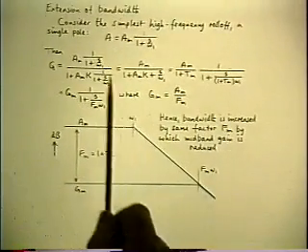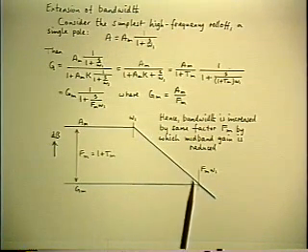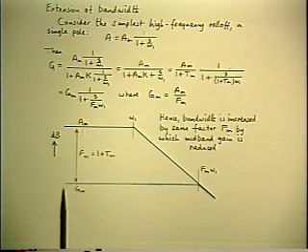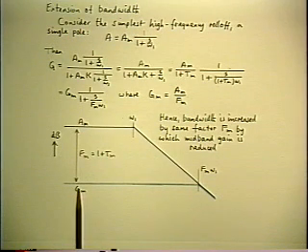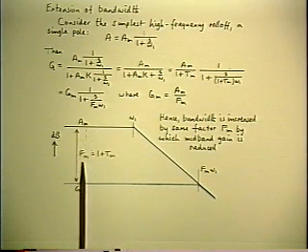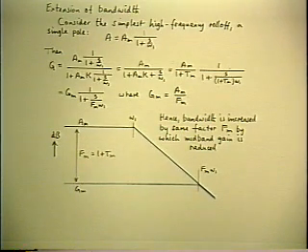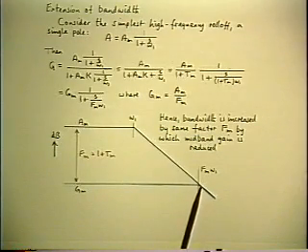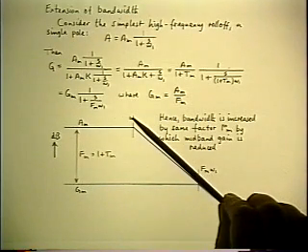So down below, I've sketched the two gains, the open loop one, which is the blue line, and the closed loop one, which is the green line. And of course, the midband values satisfy the basic relationship. Closed loop midband gain is the open loop midband gain divided by the midband feedback factor. But the important result of this picture is that the pole of the closed loop gain lies on the same asymptote as the pole of the open loop gain.